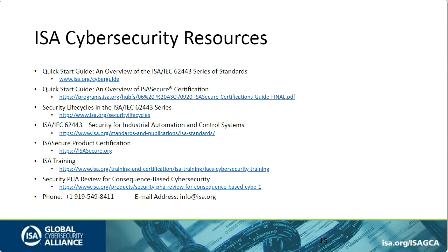And the protection level is an intention to combine the technical security measures and the organizational security measures into one entity that can be used for the assessment of an automation solution that is in operation. So, yes, it combines the technical security, using a concept in 62443 called security levels, and it combines the organizational security measures in 62443 using maturity level, to combine that into a single topic called the protection level. And so hopefully that's enough elaboration.